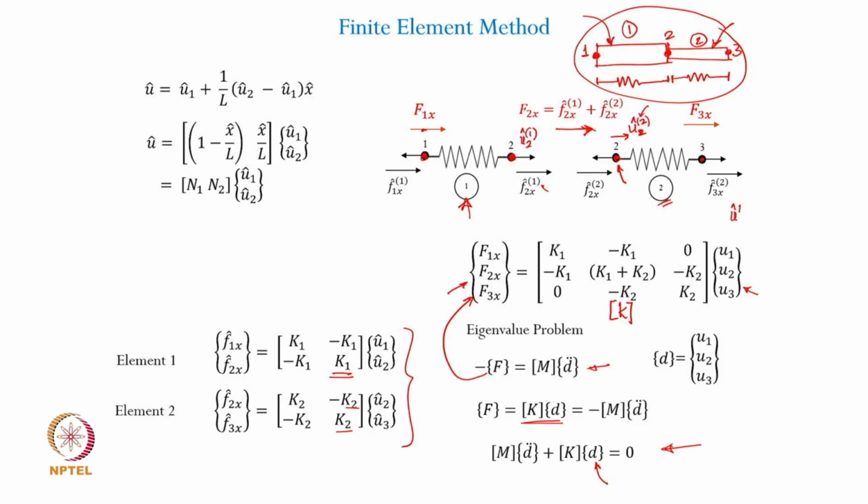This is how you set this discretization method through defining each individual element and finding out the element stiffness matrices. You can assemble these matrices together and you can see that in this case this particular element in this global coordinate system is going to be lying here in this particular position, whereas this entire matrix, this element is coming back here and that matrix is appearing here.